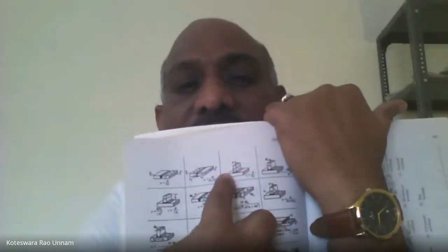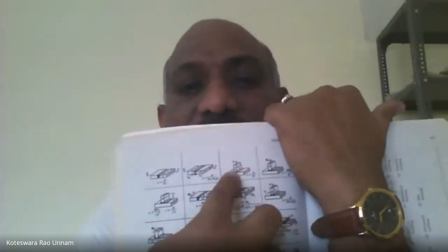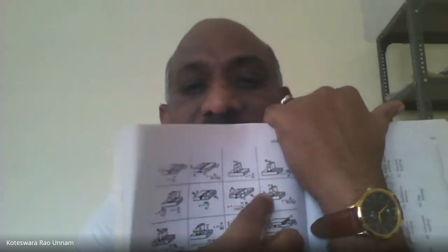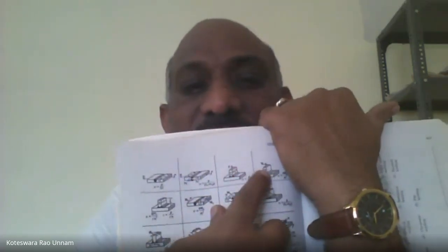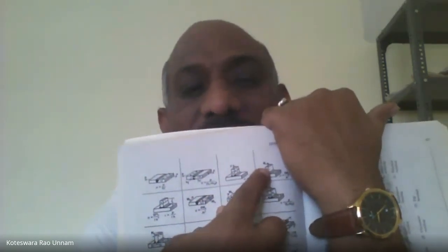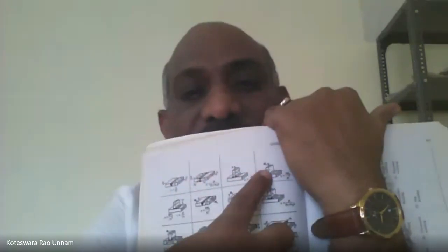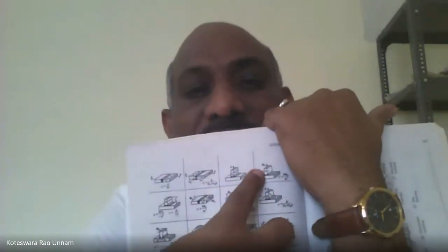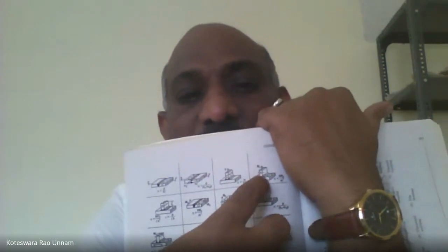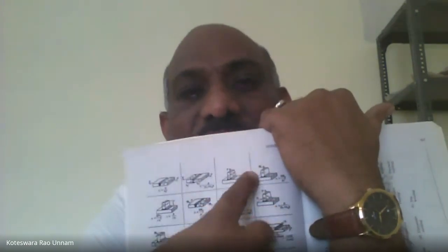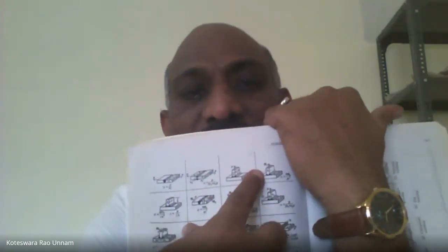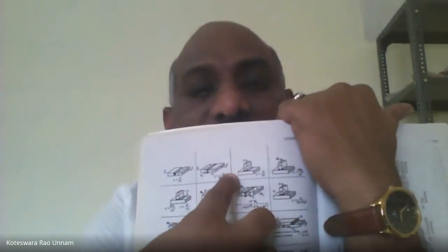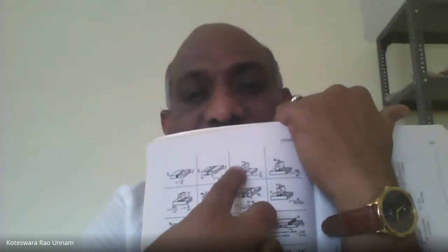Then after that you have T joints. They are also subjected to loads: in some T joints it is shown as a force, and in some T joints it is a moment. So it need not always be only a tensile force; the joint may be subjected to bending moment also. If we show an arrow upward and we are showing bending M about this vertical axis, it is subjected to bending moment. Like that, you need to read the figure. About this axis, if it is force, it is subjected to force along this axis.